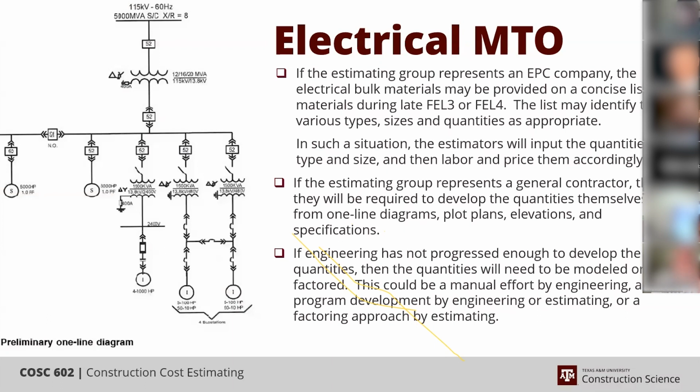Right. So that's why I'm saying that you'll have a one line from the PDC to the MCCs, because all the MCCs require a certain load, and that power load is going to come from the PDC to the MCC. If that MCC needs several, then it'll have several lines coming to it. That's right. If it's running 120 for utility, it's going to have a 120 line coming, unless it actually separates it in the MCC and then steps it down with a small transformer there, and then powers the 120.